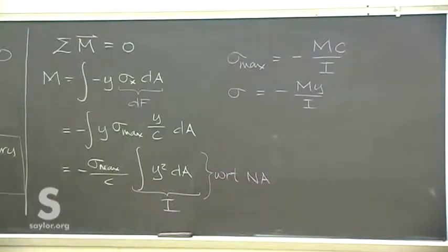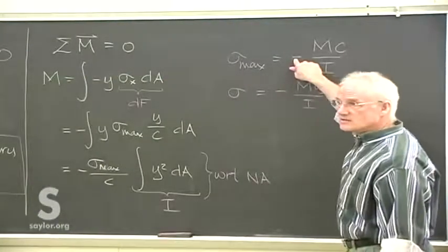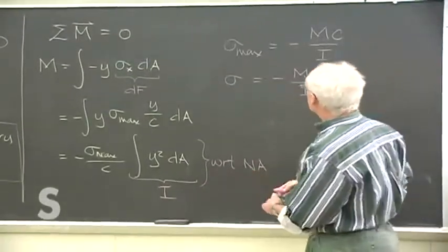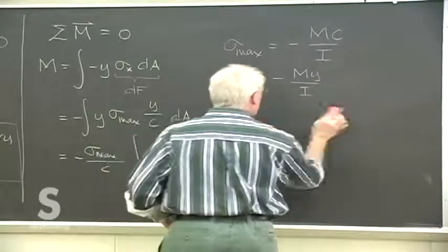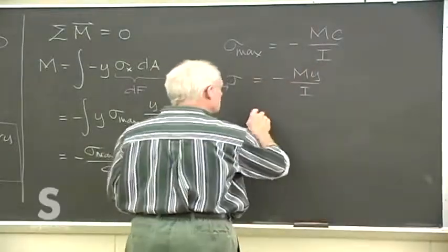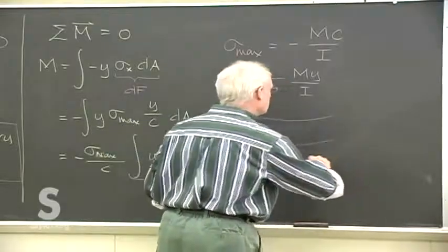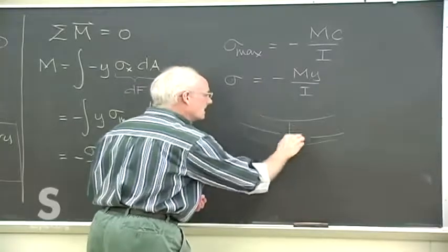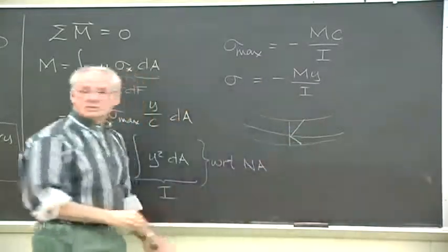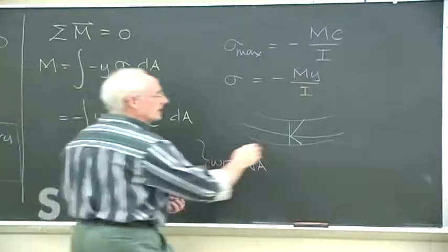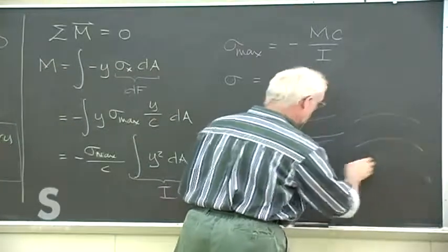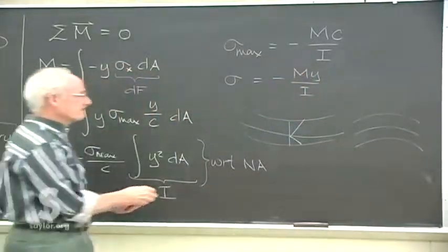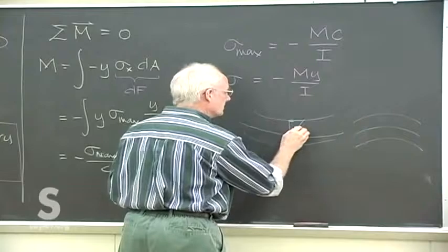What we typically do now is don't even use this, we write this down without even the minus sign being there because it's so obvious from the bending whether that's compressive stress or tensile stress because of the way these beams bend. It'll be compression above and tension below for that kind of bending, and if we have bending in the other direction, then we have tension above and compression below.